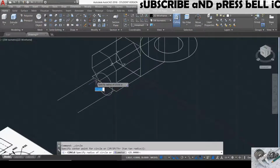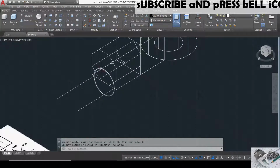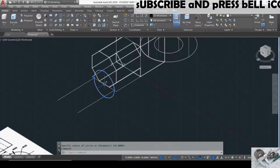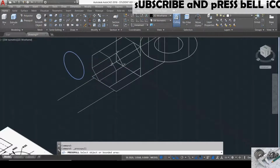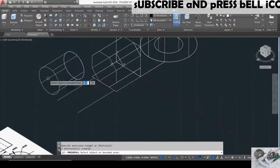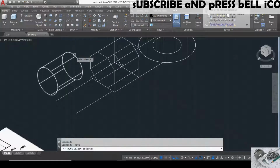Now we have to draw the shaft. So select a circle, draw it with a 12.5 mm radius or 25 mm diameter, and we will also press pull it as per our requirement. The length is not important, so you can give any length. Now move it to the proper position.